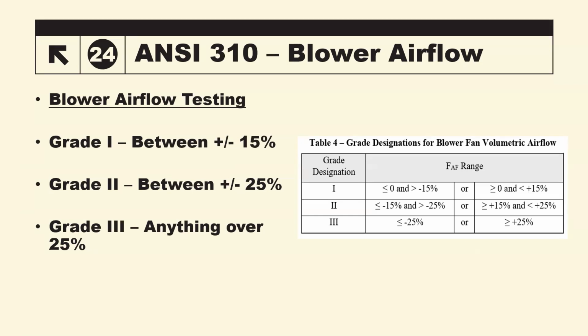Yeah, I think I have this on another slide, but to bring it up now, and it's a good point to bring it up here, is looking at fan flow. And I'll go down a rabbit hole for just a minute, because this comes full circle back to what we always have webinars for. When you're doing the testing and you say, well, we're doing a grading system of grade 1, grade 2, grade 3, how much is actually in a CFM airflow of what's actually been totally designed? So if I have a 4-ton system at 1600 CFM, if I now did the measurements by whatever means and it's different, how and why is it different?